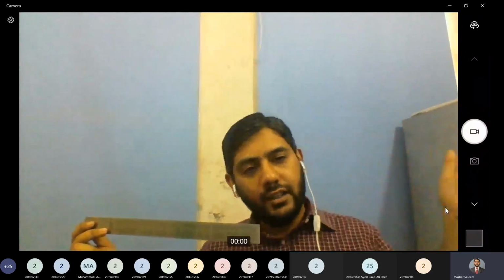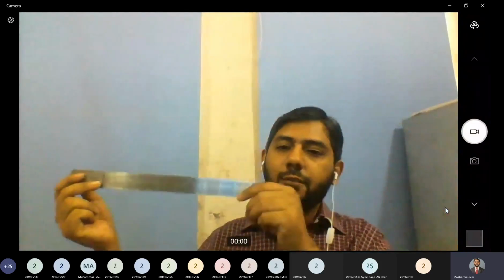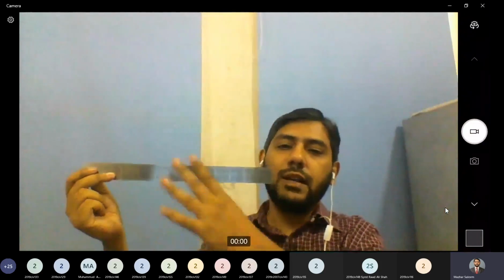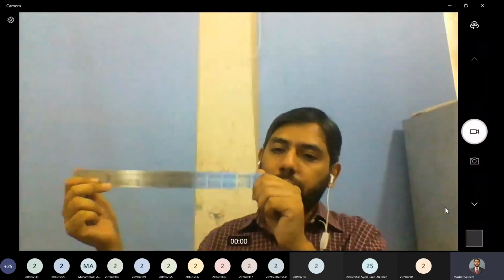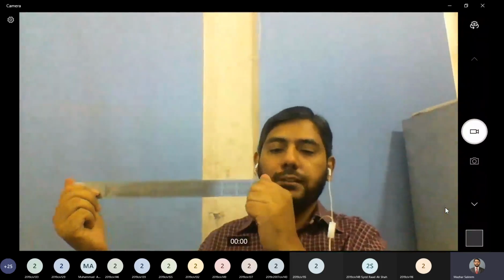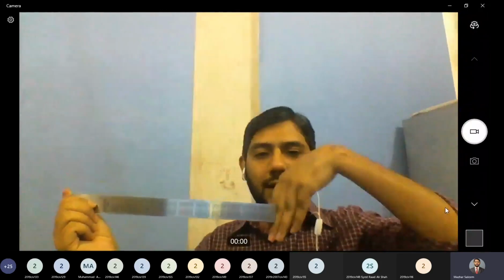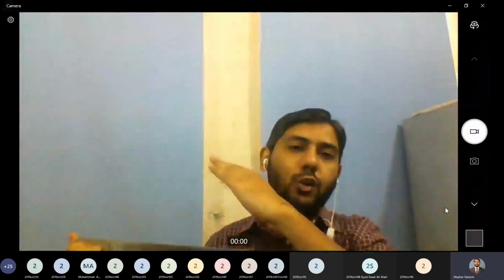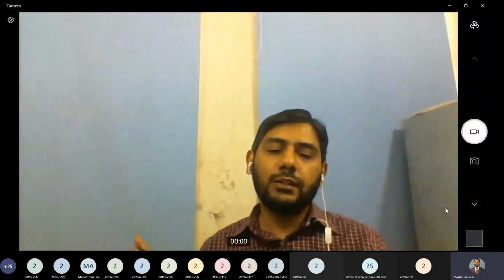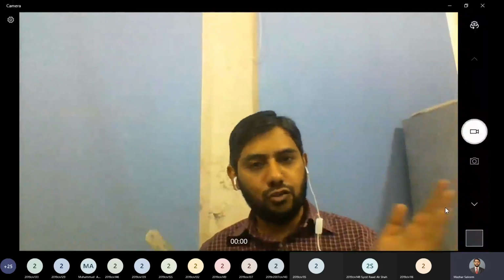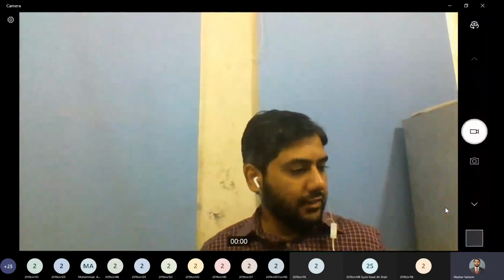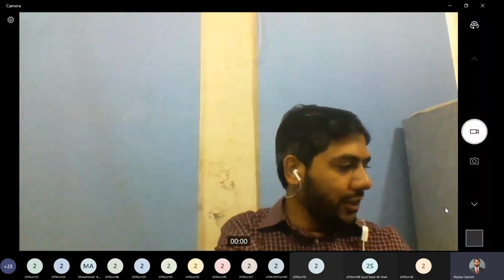These two loads act in the horizontal direction. So if the building is subjected to earthquake loading, the beam will deflect in the horizontal plane. It will either come out of the plane or bend into the plane. And similarly, under the action of wind loading, the deflection will be in the horizontal direction. And this device can be used to measure that horizontal deflection as well.